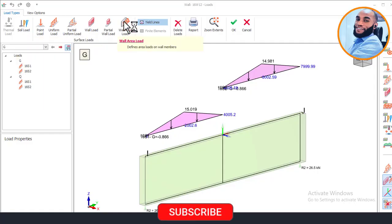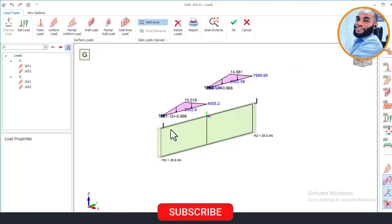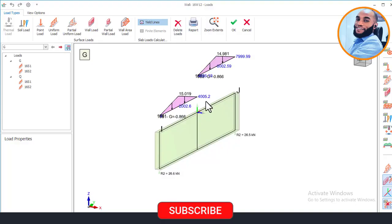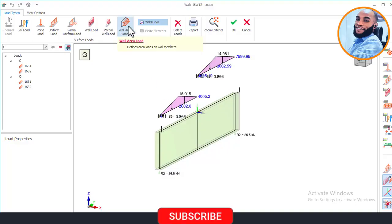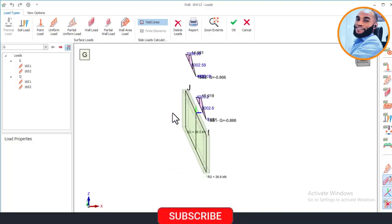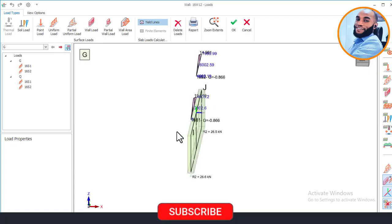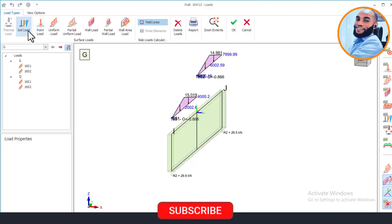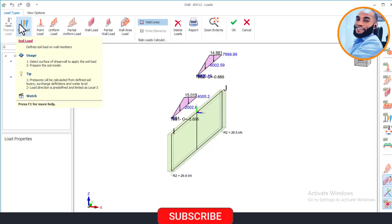With the area load, what we are trying to factor into consideration is the weight of the water from the pool that is going to act on this wall. Because of that, we are going to use wall area load, also knowing that there is no soil at the back of our wall which would cause another pressure at the back of this wall. So since there is no soil at this place, I am not going to use this soil load area to apply my load on the wall.